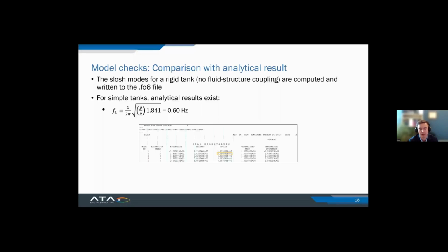No, that's exactly it. It's the same idea as with an axisymmetric model, beam bending, right? You always have your bending modes that come in pairs. So that's as it should be, right? Especially in the fluid-only modes, the slosh modes that you see in the beginning, those should for sure come in pairs. Later on in your full eigenvalue analysis, where it couples those with the actual structure, yes, then you might see maybe a little bit of a shift, which comes from structural modes not being perfectly in pairs.